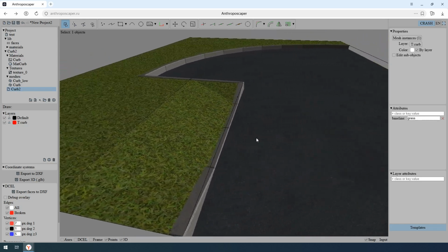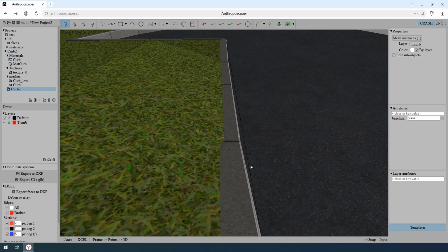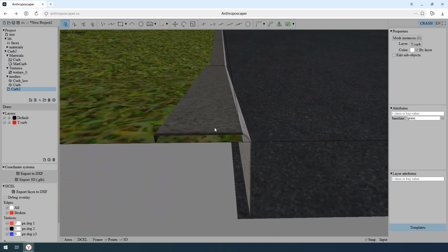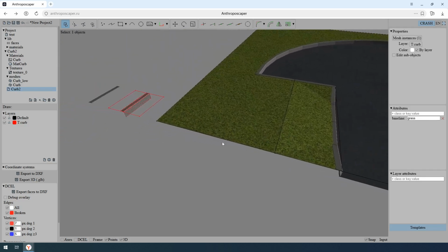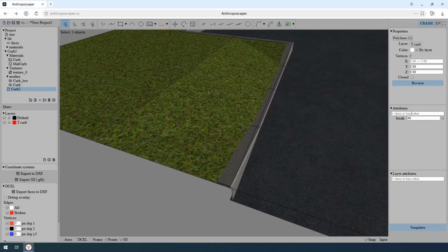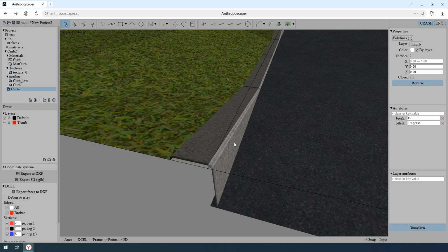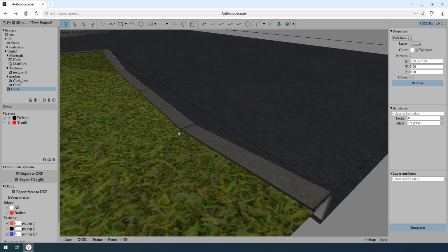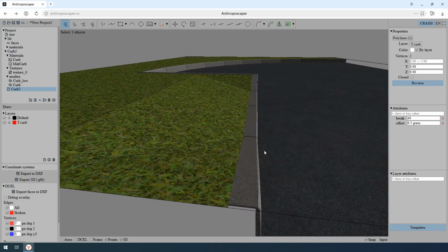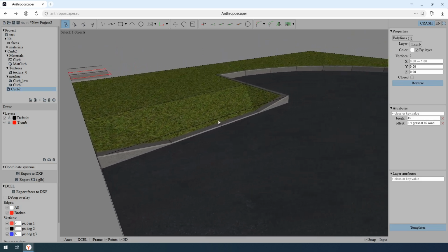Almost done, but one small thing remains. In the lowered spot, the grass geometry pokes through the curb. The face rides onto the mesh. This is solved by pushing the face's contour away from the edge. I add offset 0.1 grass to the template's axis. The grass face shifts by 10 centimeters, freeing up room under the curb, and the overlap disappears. The same grammar as dz, a number and a class. If you like, you can specify the shift for both sides at once. Now the joint is clean on all sides.